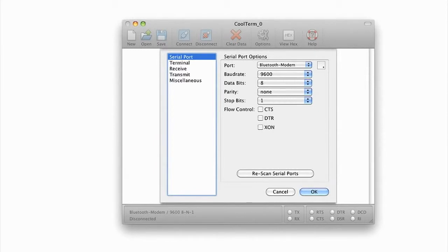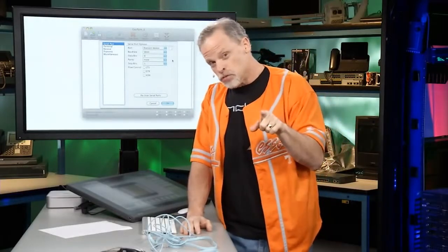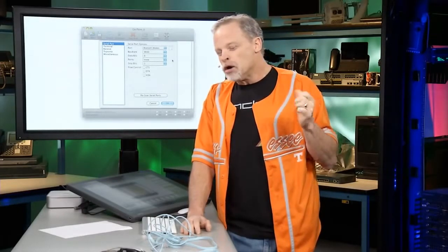There are a couple of things that you want to notice here. First off is our baud rate. When we're talking about baud rates, on equipment they must match. Now this is the key on serial communication. I really can't think of any instance where you will have something that doesn't match up. They have to be identical because they have to be able to speak.